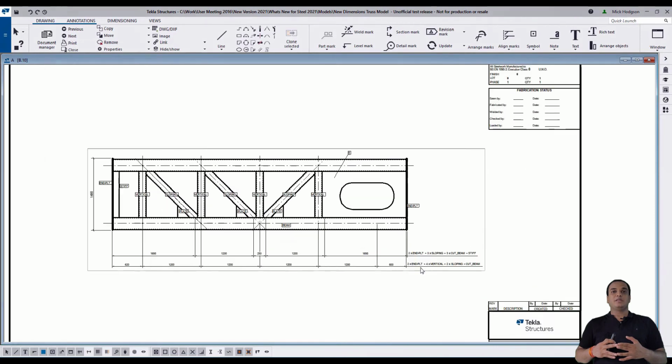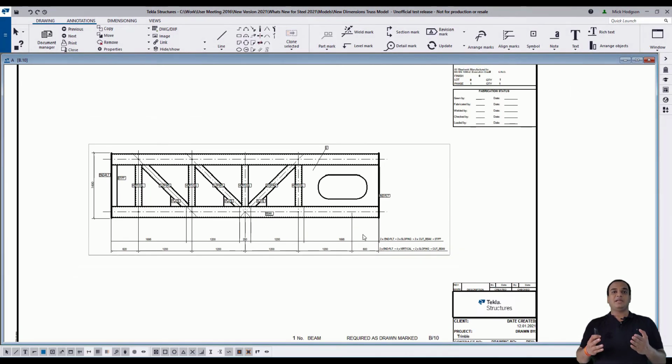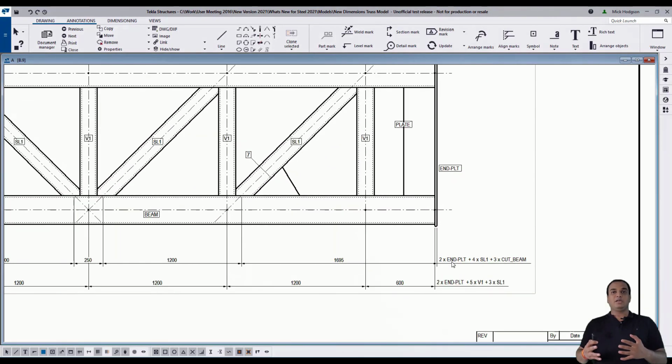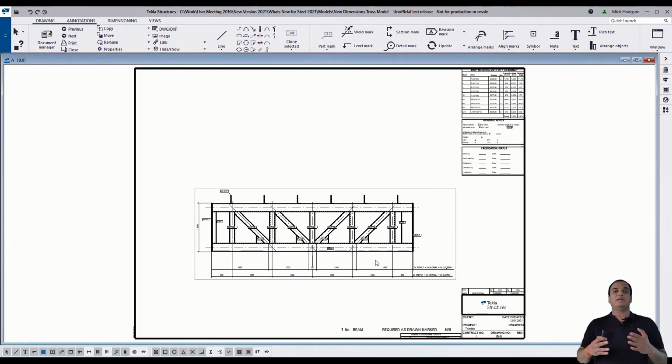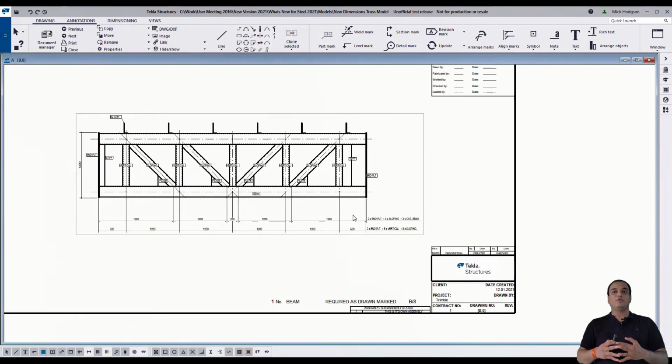So let's open the drawing, and here you can see even the tags are maintained, dimensions are maintained. Whatever you set in the associativity rule, the tag is also maintained based on that, and based on your member name here it got changed. So these are the cloning improvements.